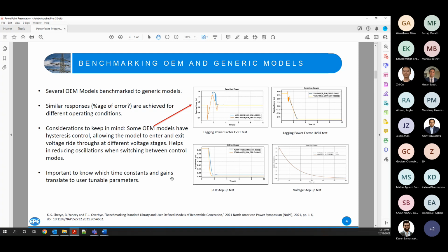So, for example, a good standard would be the inertia constant of a synchronous generator, just as an example, which you cannot tune in your study because it's a physical mass in the rotor, right? So it's very important to spend some time understanding which parameters are actually tunable and which parameters are, of course, limited to the actual physics and actual tangible equipment, and are not allowed to be changed.